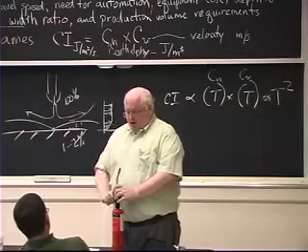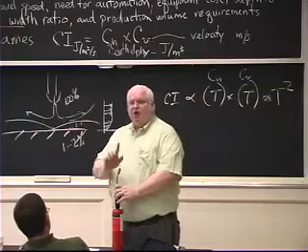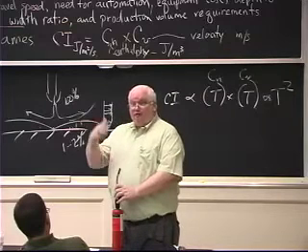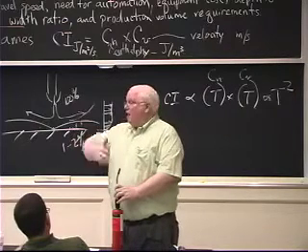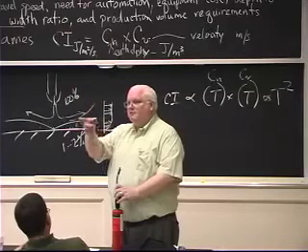Why? Because when it's a jet burner, I'm getting the burning velocity of the hot gas, not the cold gas. And that's about a factor of 10. And now I hear loud noises because I've got all kinds of shock waves as these things swirl around.